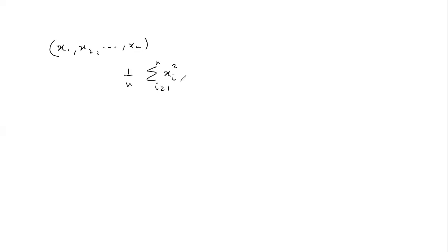Now, the additive noise in such a channel may be due to a variety of causes, okay? But you'll recall that by the central limit theorem, the cumulative effect of a large number of, let's say, small random effects will give us a distribution that is normal, okay? So if we have a large sample space, probably we're considering quite a large number of random variables, the larger, the better for us.